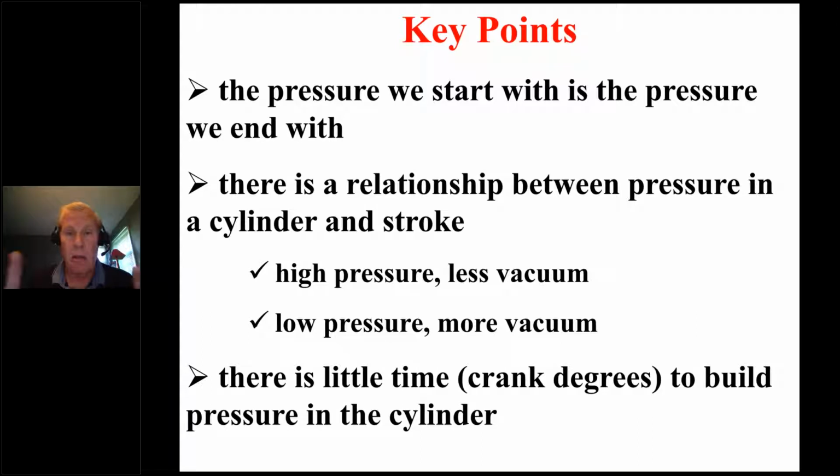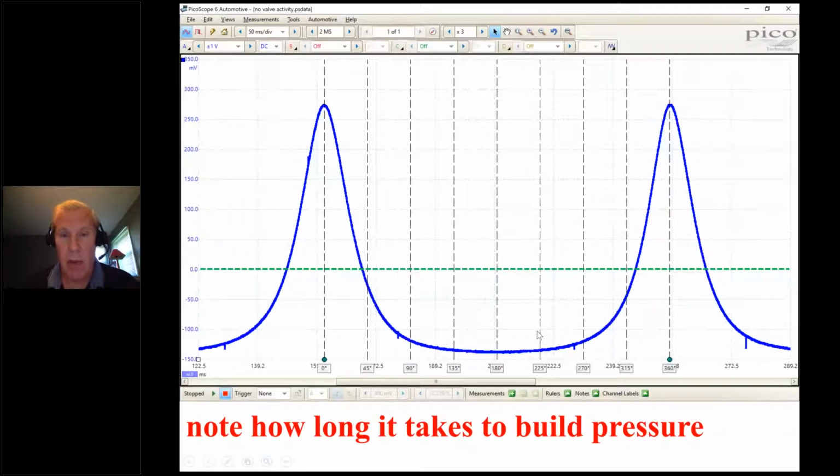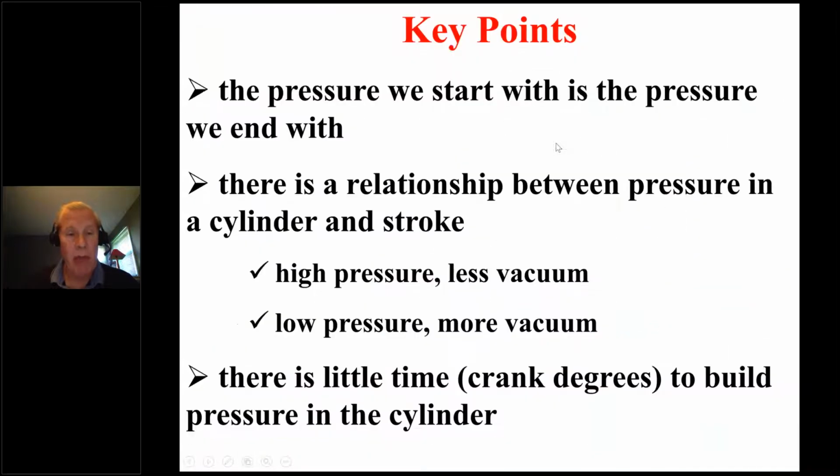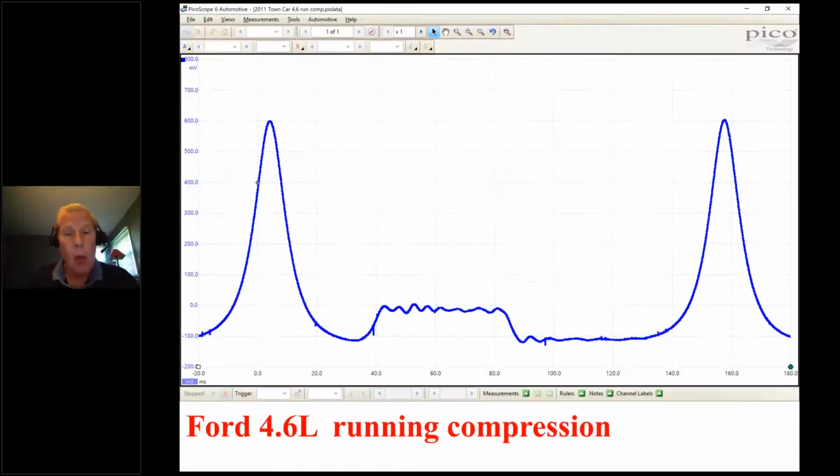And finally, my point is there's not a lot of time in crankshaft degrees to build pressure on that compression stroke, which is why everything has to be correct. So having said that, we're going to now move into what I would call a conventional, typical in-cylinder running compression pattern. I am not going to do cranking compression for a couple of reasons.